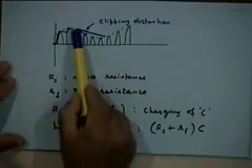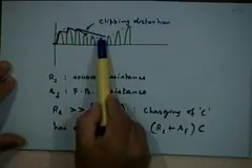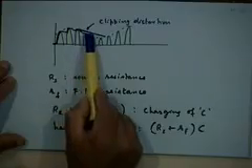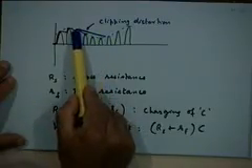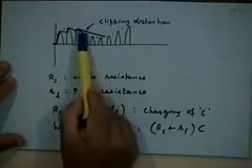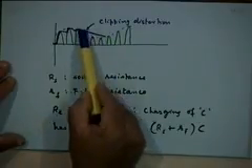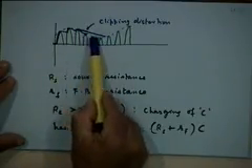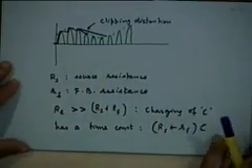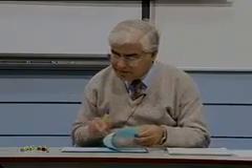You just want to make sure that while the rate of discharge is slow, it is not so slow that you fail to capture the fast fluctuations in the envelope itself, right? So you are comparing this rate of variation with the rate of variation of the message waveform, the envelope. Is that clear? So the carrier frequency does not enter into the picture at this stage.